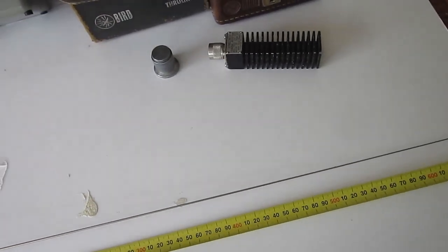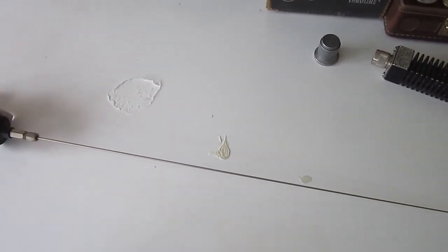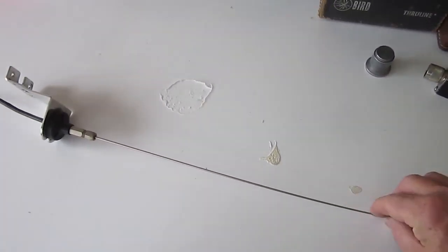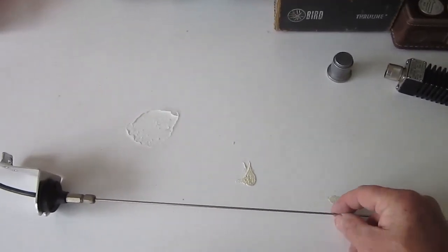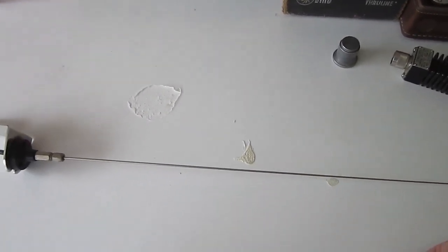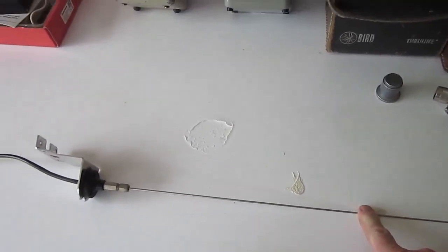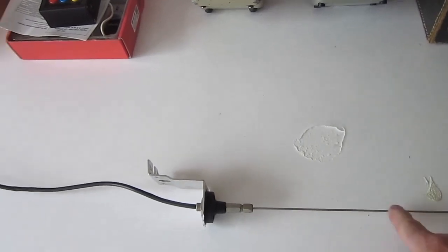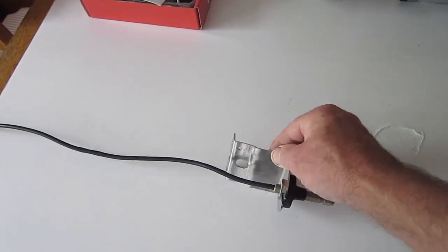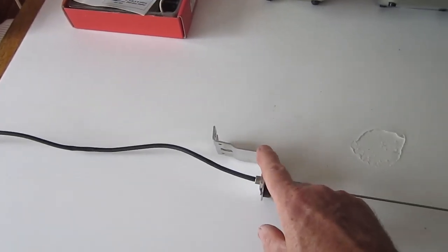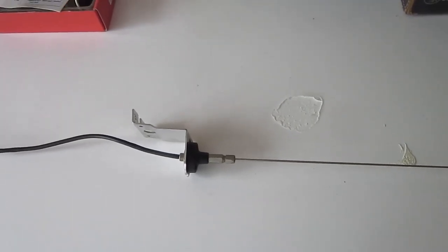However, this particular antenna is 650 millimeters long, and obviously the installer, or should I say bolter-oner, simply went to the store and grabbed an aerial and bolted it on. So not only was this not adjusted for length, but although this is a quarter wave whip and requires a ground plane, you can tell from the bracket that it's been bent and I've removed it. This antenna on the vehicle was installed in a location where there was little to no ground plane at all.